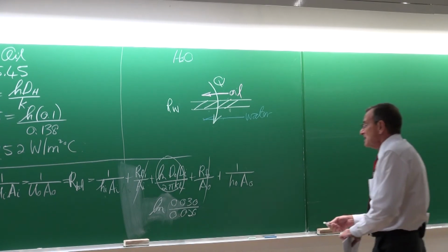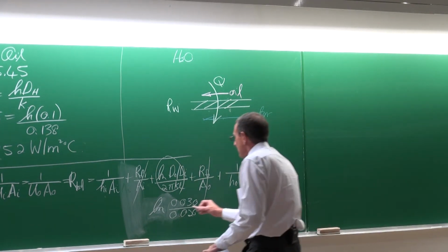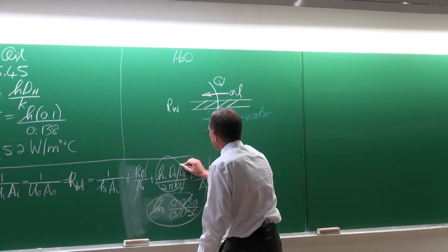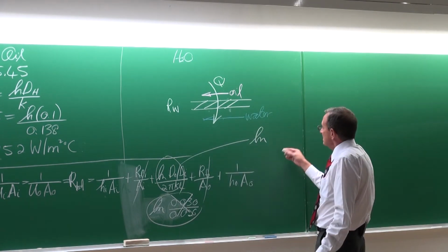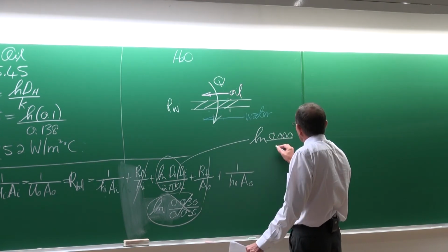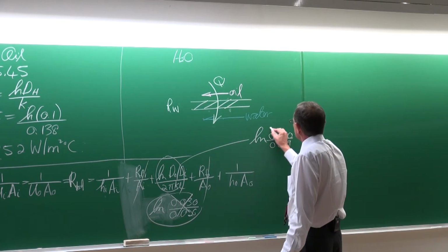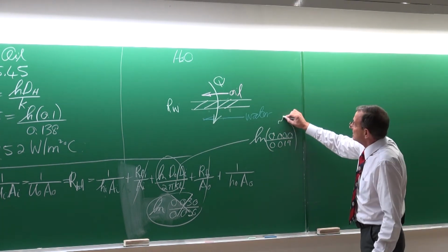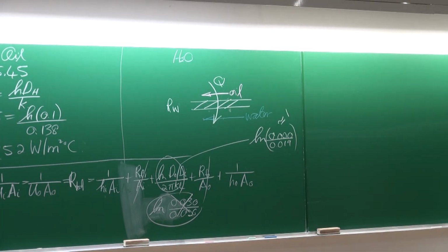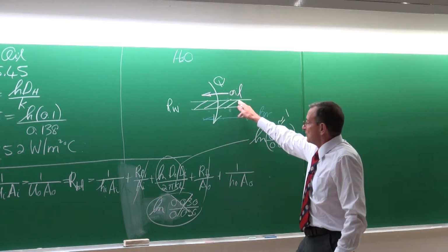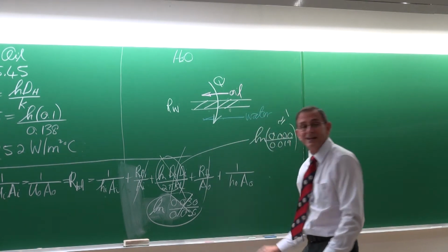They actually said it's thin. Okay. So if it is thin, it means that this term is obviously incorrect. Thin would mean that on the outside maybe it is 20 millimeters, and on the inside it is 19 millimeters, the ln of something like that. And that would be approximately 1. You agree? If it's a very thin wall. And the ln of 1 is equal to 0. So the moment we've got a thin wall, that resistance is also negligible.